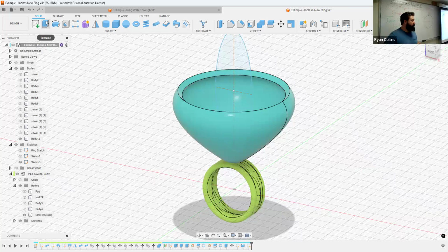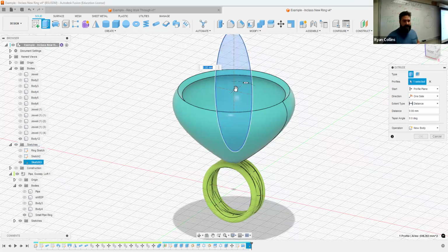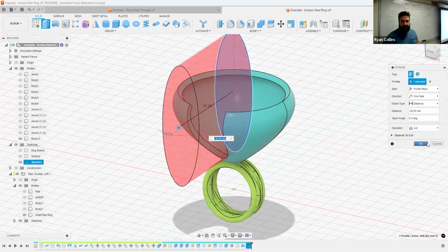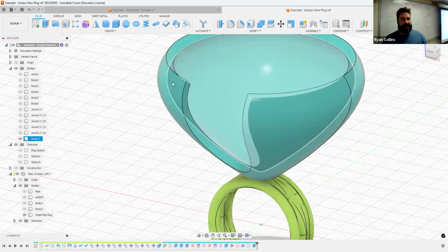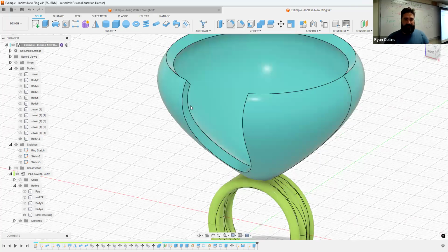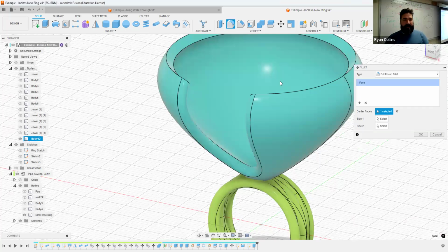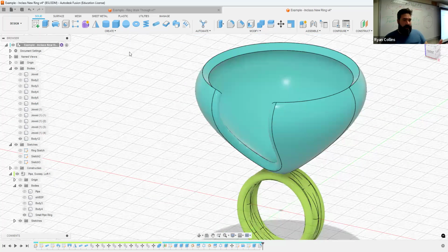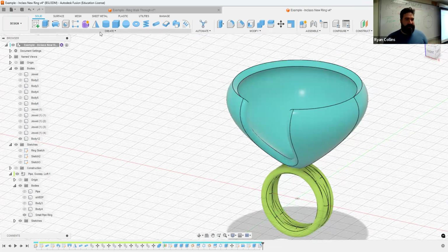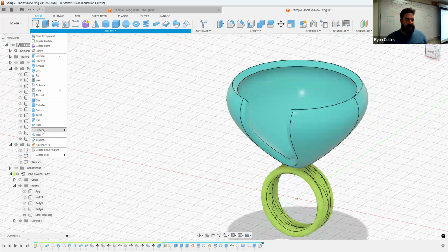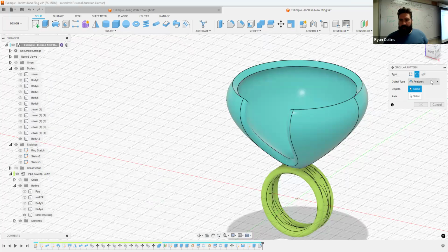So from there, like we did before, just going to use that sketch, extrude it forward so it does in fact cut. Okay. Make any modifications I need here, or I can do it afterwards. Now let's make some fillets there. We'll see if I can do a full round on that internal. Let me do the same thing from above. Probably should have done that already, but okay, we'll just finish that. All right, so from there, just like we did before, again, circle pattern, features.